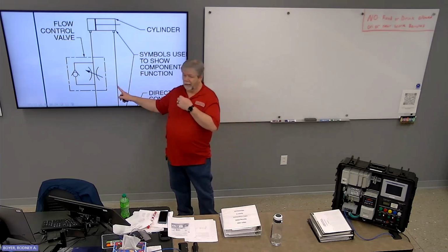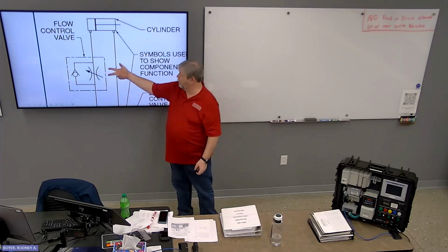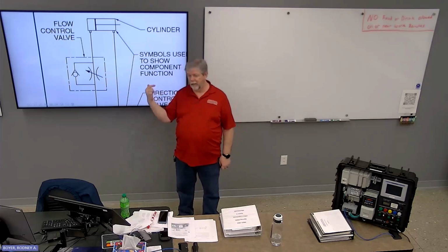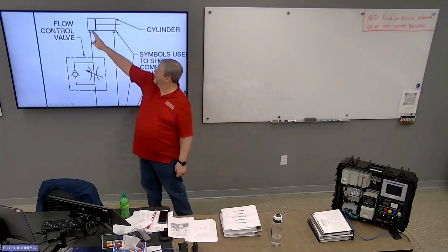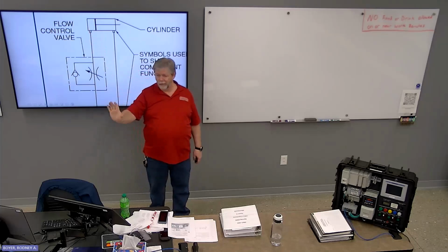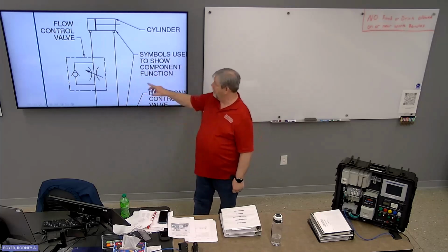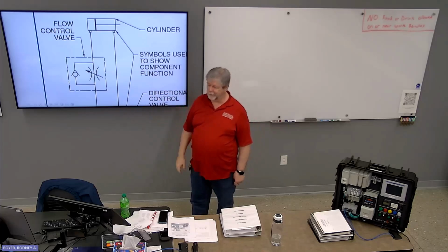That should actually be in this line, and it should be flipped over. Gotcha. So you can retract at full speed, but you meter as it's going up. So put your pressure here, it's going to be pushing on whatever load it's connected to. You can have one on both if you need to control flow in both directions. That takes us to the review and the activities, which are separate and on Canvas.